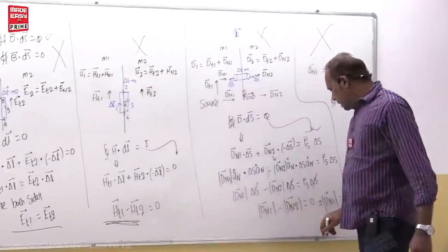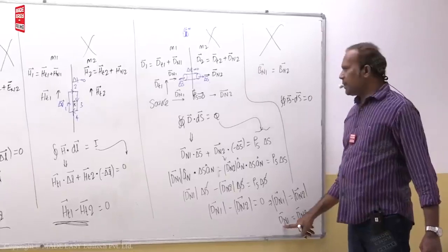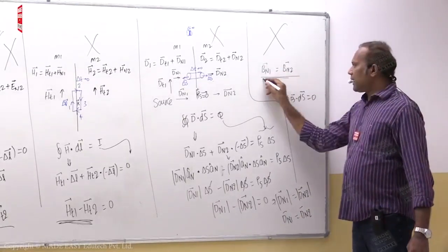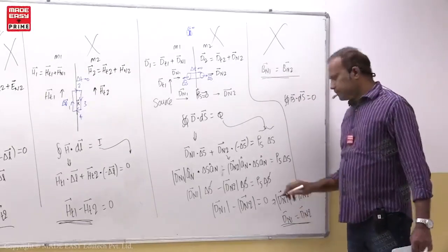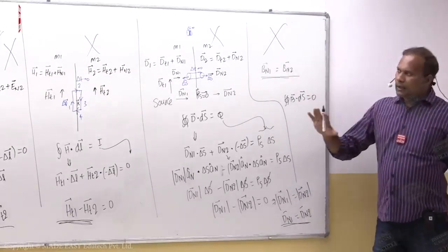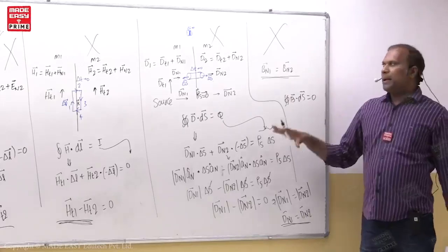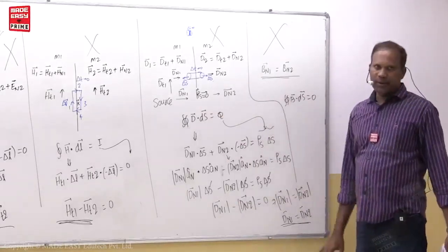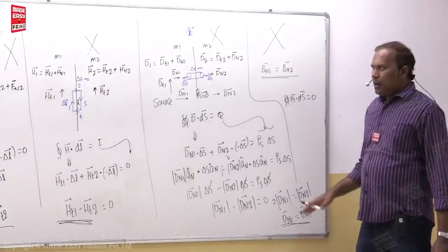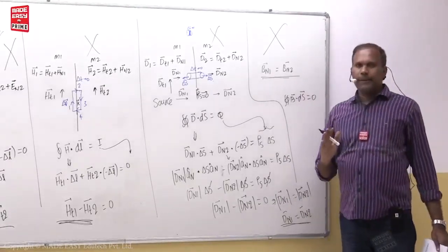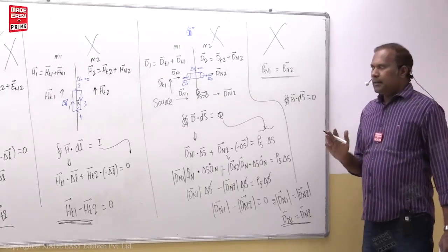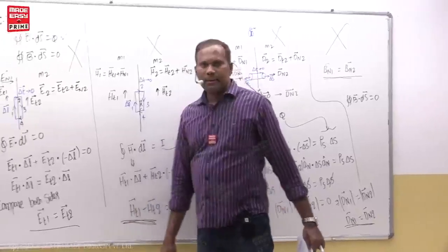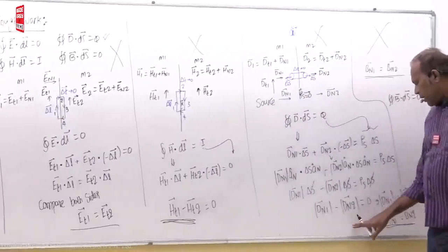For densities, this is also a density, electric flux density, and this is also a density, magnetic flux density. For densities, we get normal relations. That point is to be remembered from these things. These derivations are not at all useful, students. So what did you observe? Boundary conditions mean we get tangential relations for intensities and normal relations for densities.